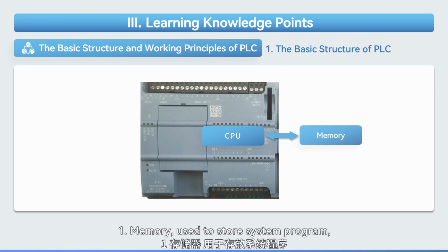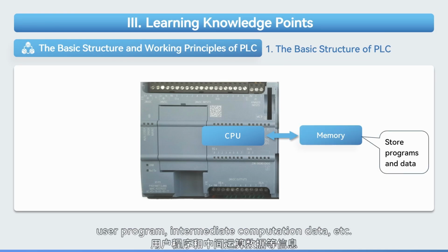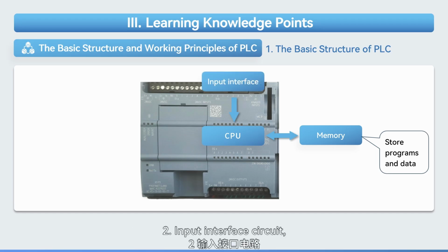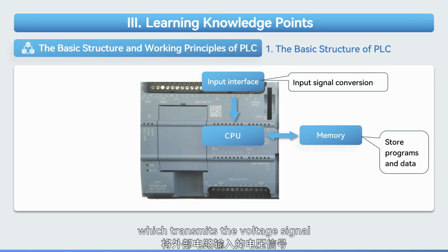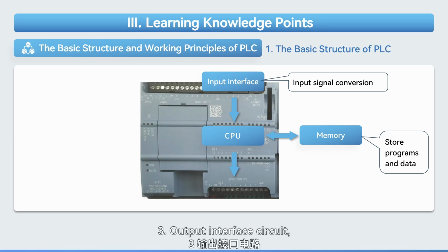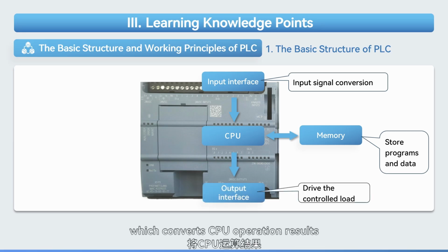1. Memory, used to store system program, user program, intermediate computation data, etc. 2. Input interface circuit, which transmits the voltage signal from the external circuit to the PLC internal circuit through the optical coupler. 3. Output interface circuit, which converts CPU operation results into output of a certain power form to drive the